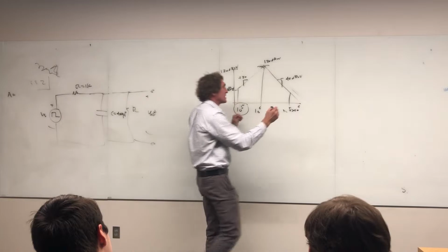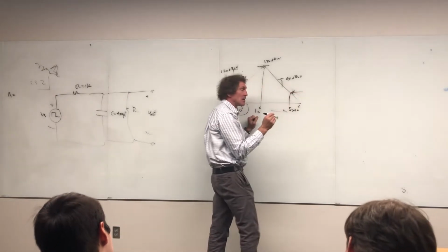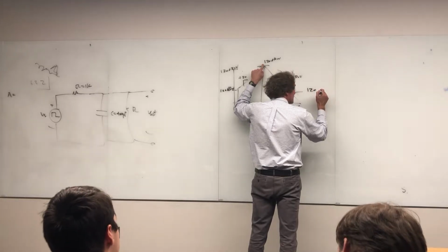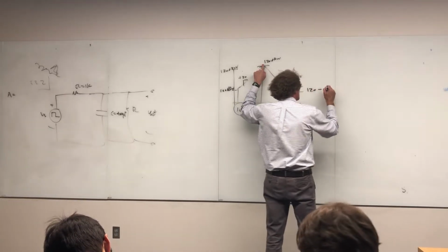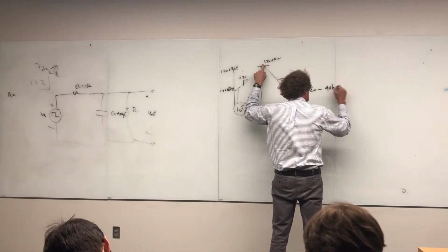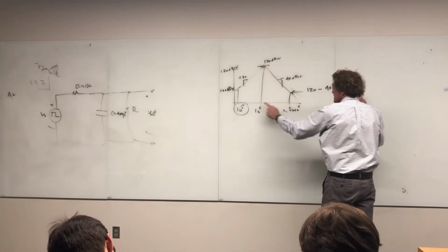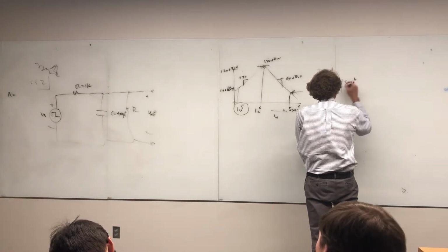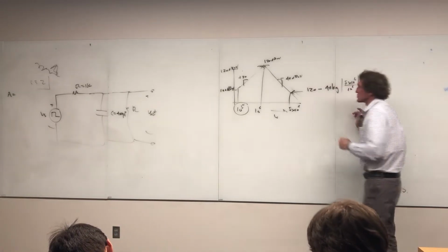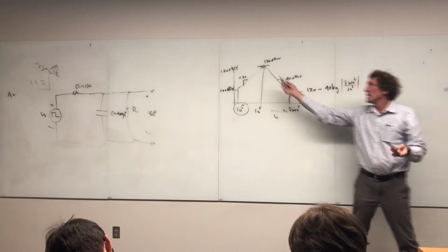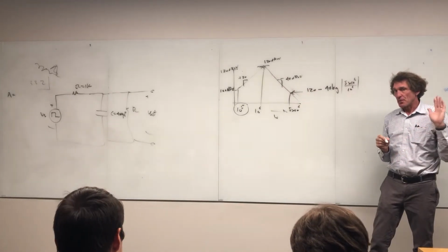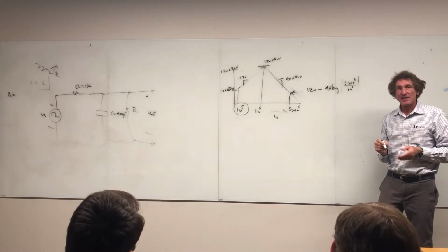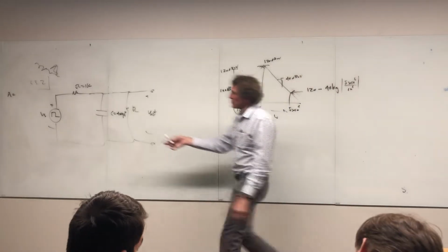So what we have to do to get the level of the signal strength right here, we start here, we have 120 dB microvolts, right? Mm-hmm. And then it's going to be minus 40 times the log of 5 times 10 to the 6th over 10 to the 6th. Now that means it's a ratio of the frequency you end up at divided by the frequency you start. I put the minus 40 out there because it's going down. Does everybody understand that?